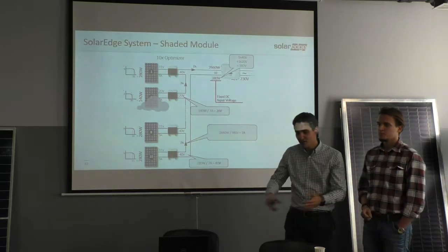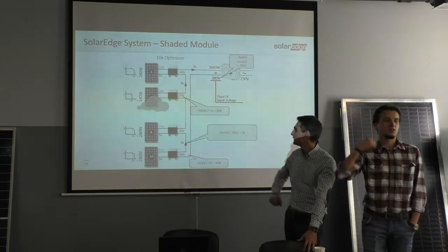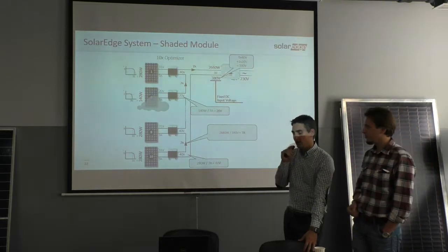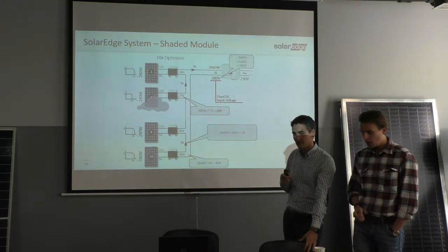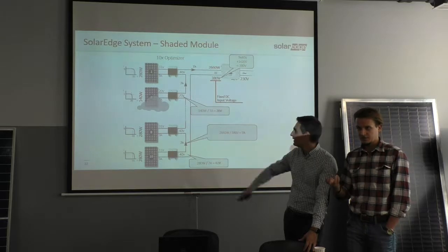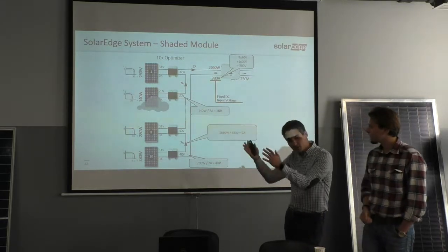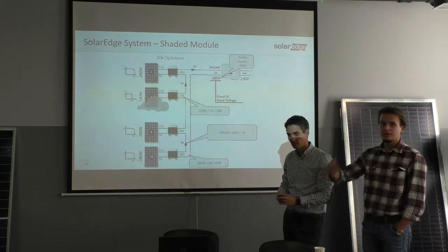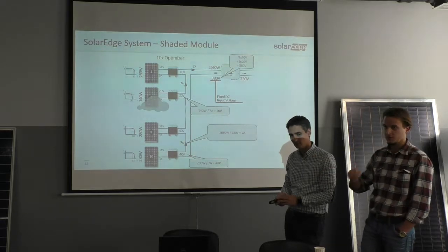This is advanced training, and we chose a special situation. What happened here? That is a topic for a much more serious, separate training. That would be the truth if there were no bypass reaction. But here we have a bypass reaction: the really shaded part of the module was bypassed.